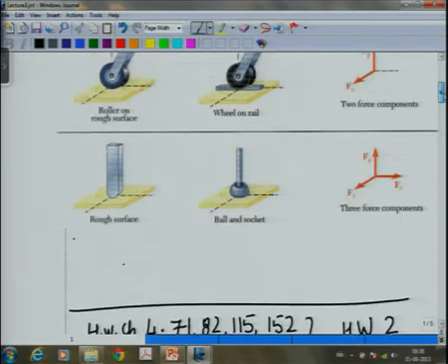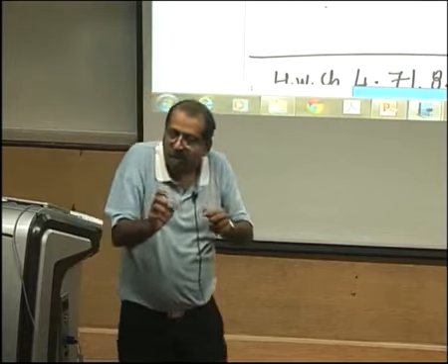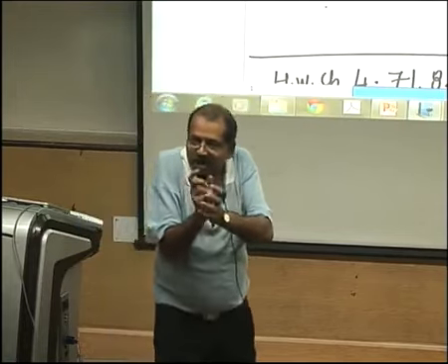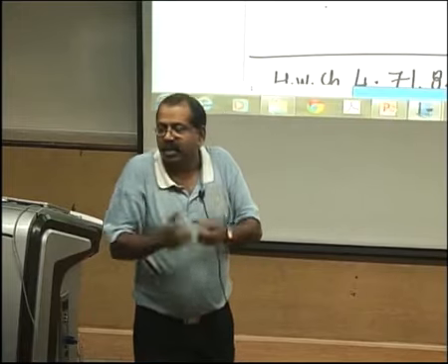Now, the torque could come, because if you try to rotate this about, let us say, an axis which is marked as z, then it will be prevented from rotating. So, the torque should come, but we assume that there is a point contact, and locally there will be a small deformation, so that it will just deform and there will be no torque.